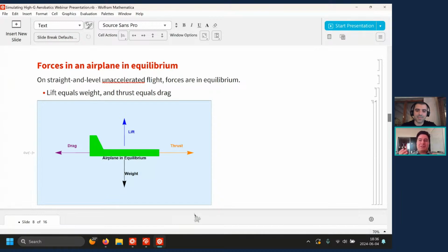But yes, as long as you're not trying to do something outside of the range of validity of a normal airplane. If you want to try to simulate an airplane this small, maybe that's going to be quite weird because then the Reynolds numbers behave weirdly. But if you try to do a fixed-wing airplane of 1 meter of span, or all the way up to the jumbo jet, you should be on the safe side. Okay, yeah, thanks for that.